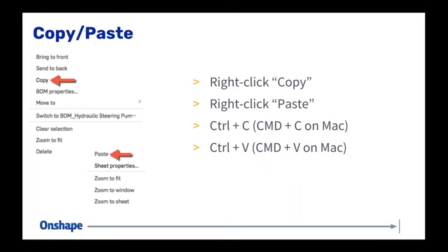There's no way today to copy and paste views, but you can move them, and I'm going to show you that in just a moment. But other things like notes, like tables, if you need to insert the same thing in multiple sheets, you can right-click copy, right-click paste, or Control C, Control V, Command C, Command V if you're on a Mac.